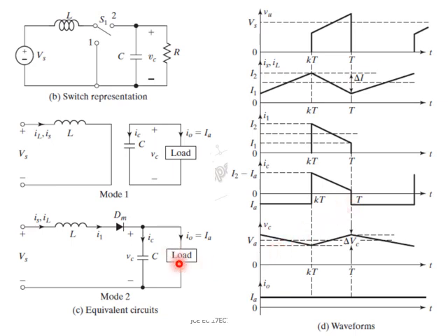Here we are seeing the capacitor voltage. When the load is discharging through this capacitor, the voltage is slightly dropping. And in mode 2, when this current is charging the capacitor, the capacitor charges. So there is a ripple voltage that is going to come across this capacitor. All the ripple current will be going through this, and hence the average value, which is equal to the output load voltage, will be coming across this. So delta Vc is the ripple voltage across the capacitor, and delta I is the ripple current flowing through the inductor.